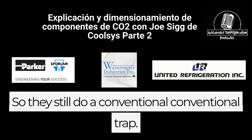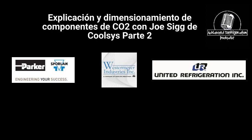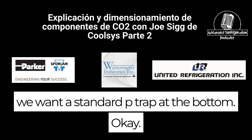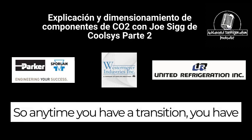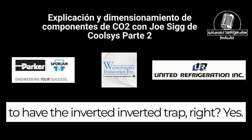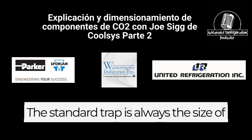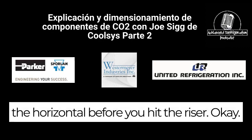Okay, yeah. So they still do a conventional trap. Yep. We want an inverted P at the top, and we want a standard P trap at the bottom. Okay, so anytime you have a transition, you have to have the inverted trap, right? Yes, and the inverted trap is always the size of the riser. The standard trap's always the size of the horizontal before you hit the riser.